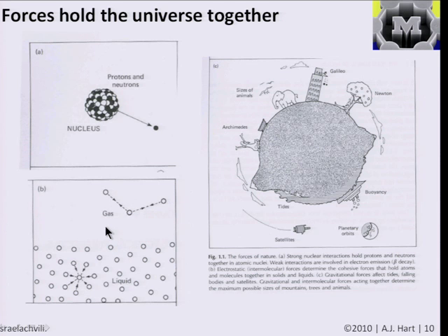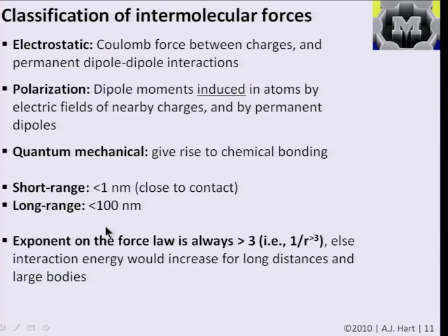And these operate on the length scale range of fractions of a nanometer to tens of nanometers. And even over that range, there are substantial differences, for example, in the forces felt between two bodies. If you had two surfaces that were perfectly flat, say they were atomically flat, and you held them a couple nanometers apart, they would be feeling an extreme pressure, many, many atmospheres between them. But if you had them, say, 10 nanometers apart, the pressure would be a small fraction of an atmosphere. And that means that at contacts between two macroscopic bodies that have a finite roughness, at the location of where the atoms actually contact, where you say have two atomic mountains contacting each other, because of these interactions, the forces and the pressures are in fact very high, and we'll see where that comes from exactly today.